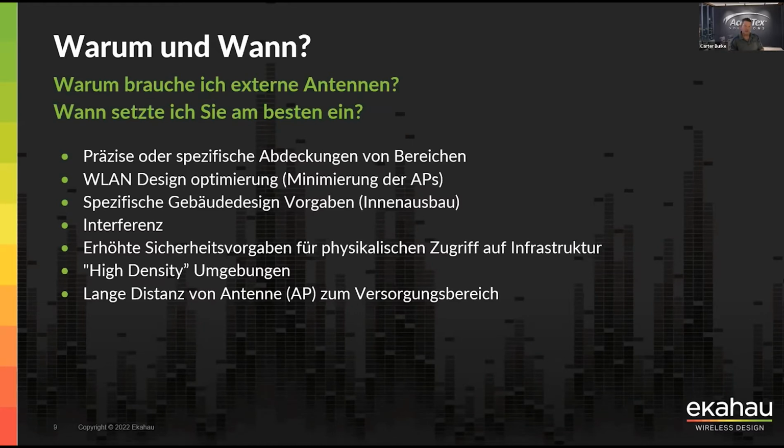So one of the number one reasons you're going to use an external antenna is when you need that focused coverage or focused cells of coverage. Sometimes you're trying to make smaller cells of coverage just to have more throughput. So that focus is very important.